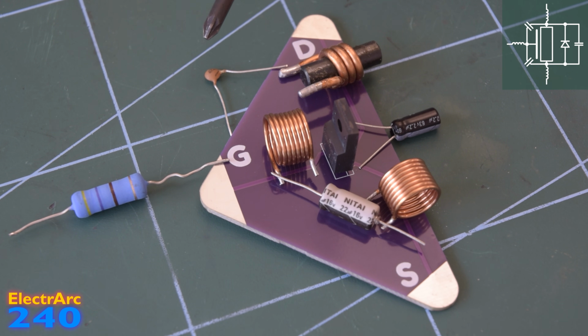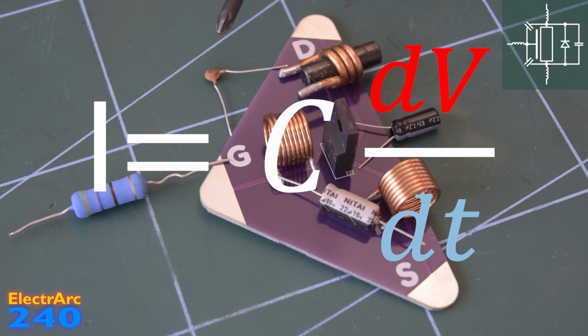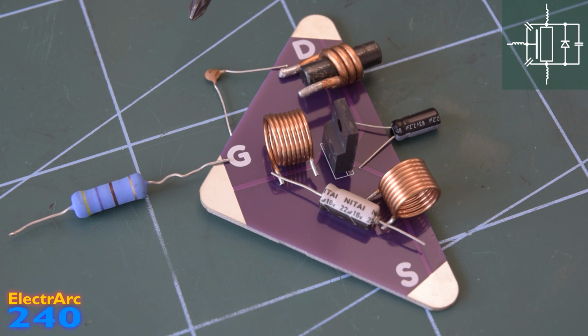So looking at our capacitor current equation, we've got a bigger change in voltage in a smaller time. So that means the current through this capacitor that's going to be trying to charge up the gate is much higher. Luckily, we are mostly saved from this by our old enemy, the gate source capacitance. That's because this capacitance is much, much bigger than the gate-drain capacitance. So together they form a capacitive divider, and most of that current that flows from the drain to the gate through the Miller capacitance is just soaked up by the gate source capacitance.